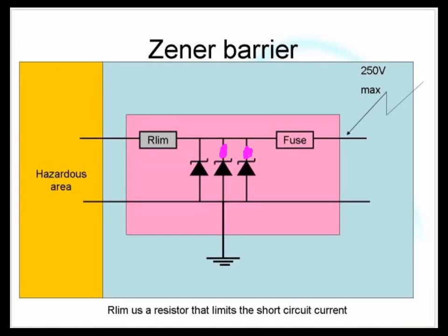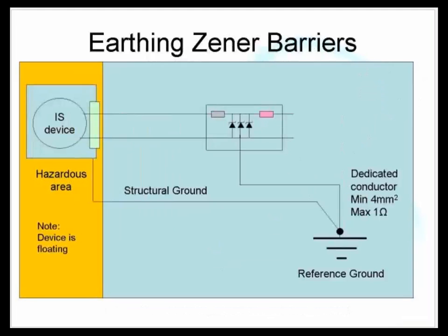So that is one problem with Zener diodes. You can even be in a situation where you don't have any diodes working, and then you're in strife, because the 250 volts, if it shorts onto that contact, will go straight through, and we have got a problem.